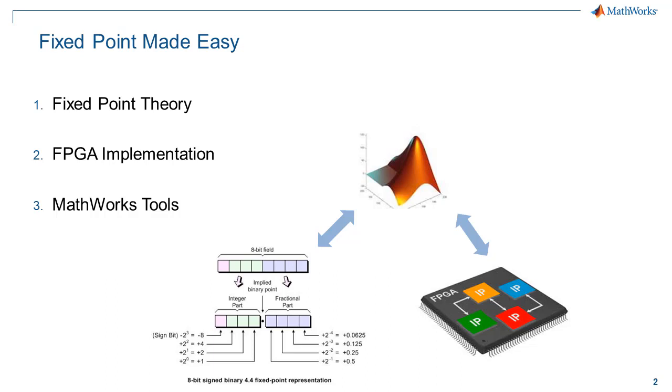So understanding of the theory of fixed point mathematics, hardware architecture, and FPGA implementation concepts, and then how to express those together in MathWorks tools. And if you can pull all that knowledge together, you can do really, really well taking a floating point design all the way to implementation fixed point on an FPGA.